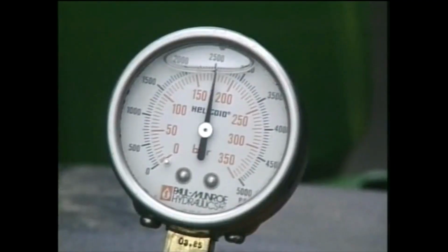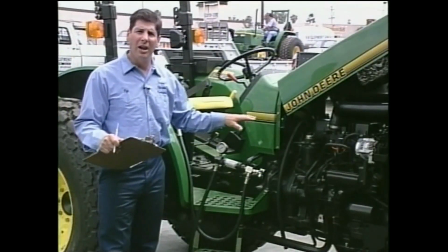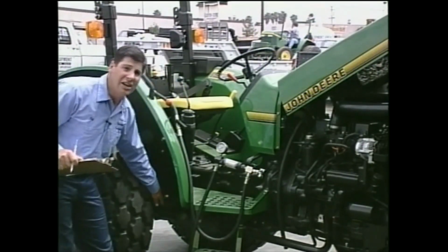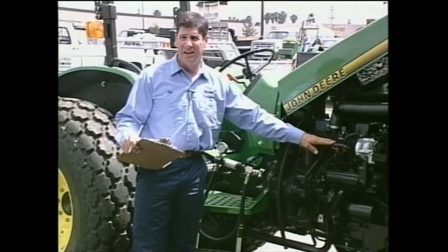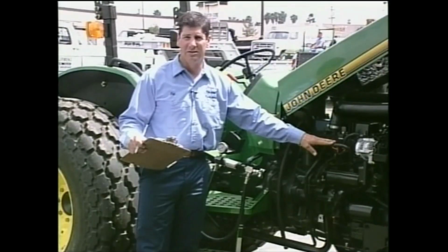Now, very slowly and carefully, bring the system up to full pressure. Read and record the pressure and flow meter readings. If the system is warmed up, the reservoir oil level is not low, and the suction filter is not restricted, the pump should be replaced if it pumps less than 85% of new pump specifications.